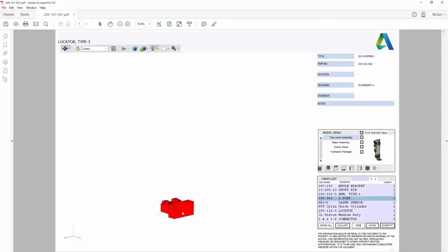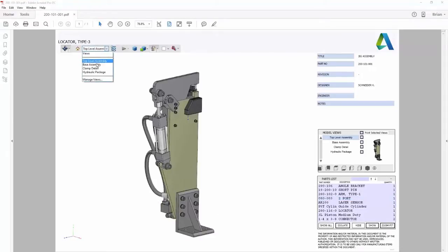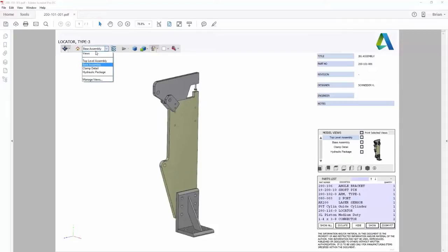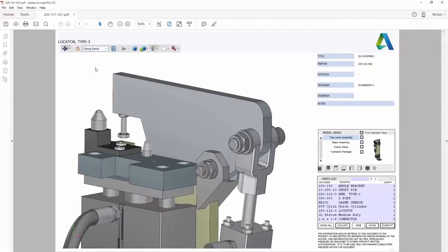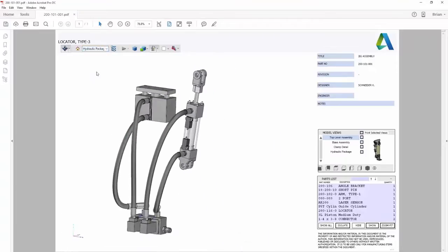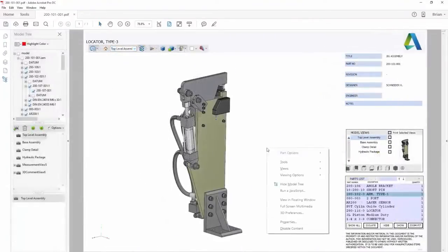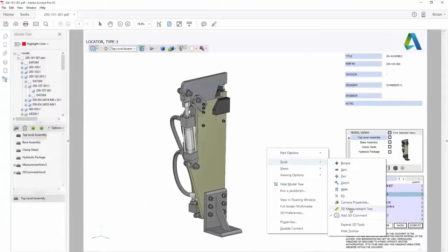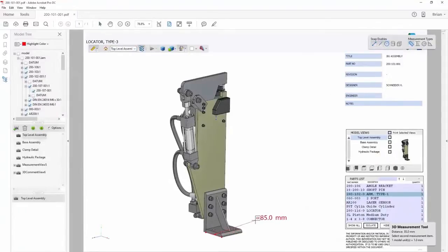You can zoom, pan, and rotate the model, view the model tree as it was configured inside Inventor, and adjust the visibility of individual parts or subassemblies. If you exported multiple design view representations, you can select any of the views to display the corresponding model inside the window. 3D PDF files are also a useful medium for conducting design reviews.